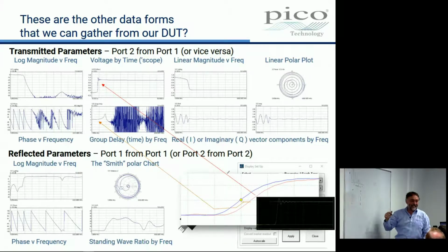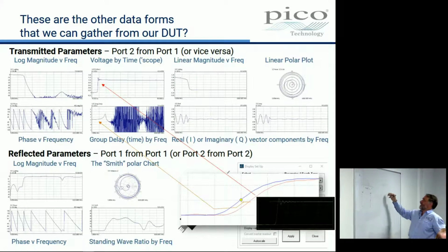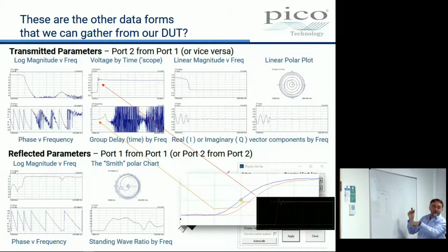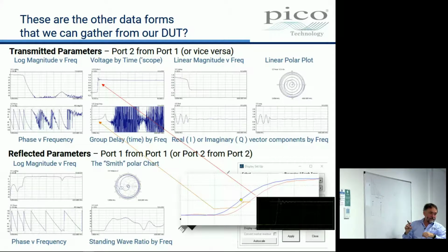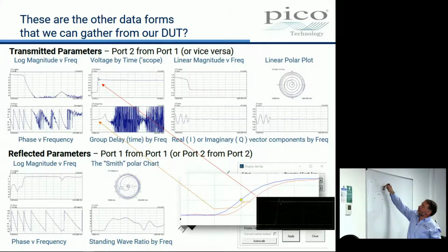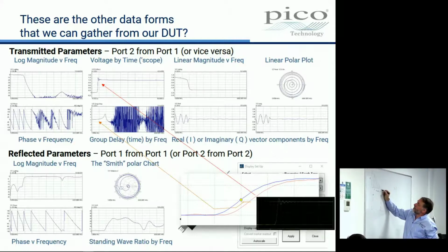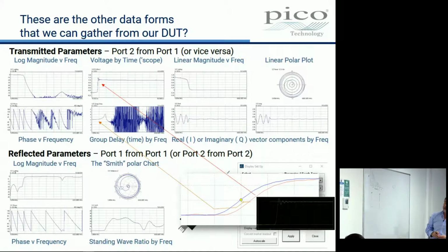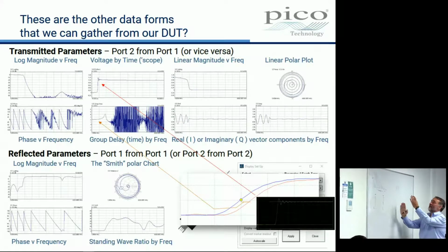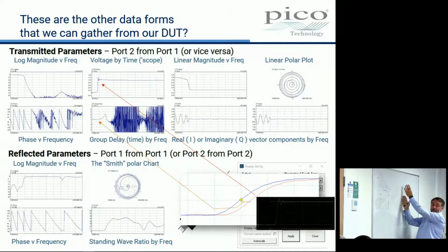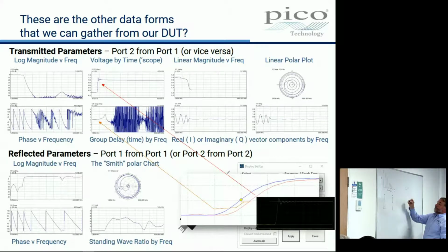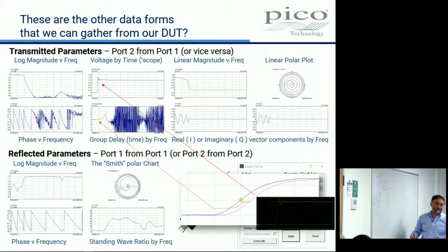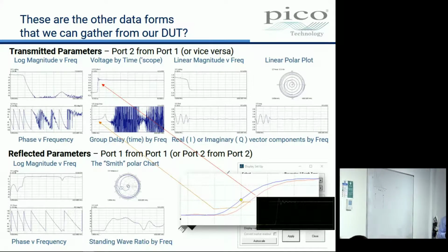Sorry, I've not drawn this quite right, but all of the harmonics add to make my square wave, right? But what if some of them were delayed by 4 nanoseconds, and these were all delayed by 2 nanoseconds? Oh God! All these harmonics are going to start to misalign with one another, and this is what happens. Seen that before? Group delay.